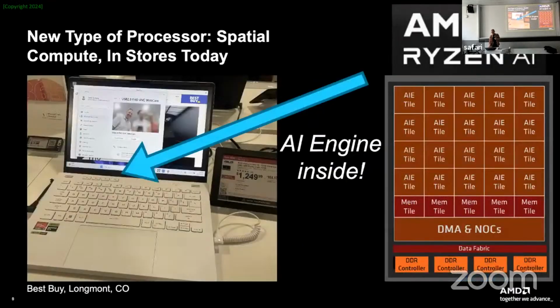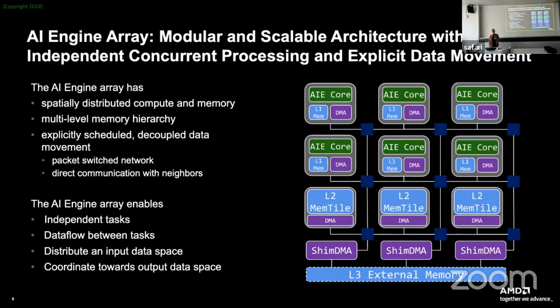One other question is, so this whole thing is tailor-made for neural network inference? So that is a very important application domain, exactly, but it can also do other regular types of signal processing. So it's a generic architecture as well, as long as they are not overly random and overly sparse in a random way, so that you can properly express all of the communication that needs to happen at a granularity that this hardware supports. You can support any type of signal processing as long as the compute operations, of course, match with the type of vectorized operations we offer in the AIE core and the compute core itself.